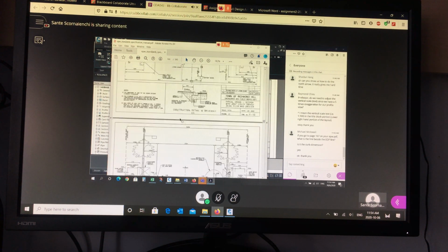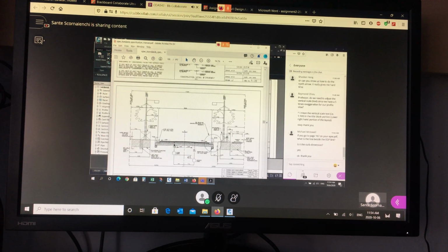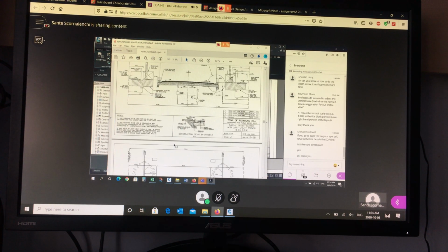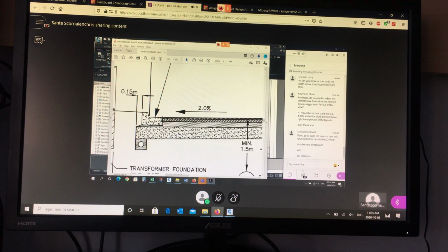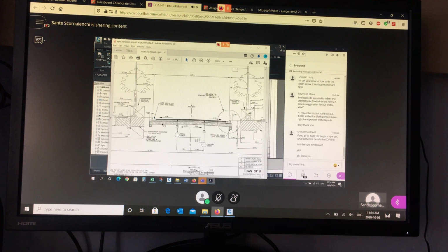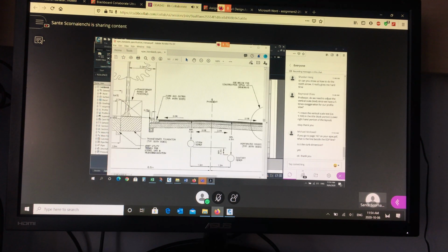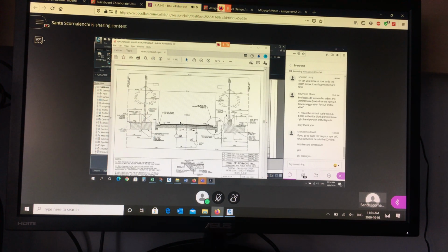Some standards will show you this is the gutter line. This one. Okay, local roads and collectors aren't that big a deal. But if you go to a freeway or an arterial road, the pavement width actually is from edge of asphalt to edge of asphalt. That width of the gutter is not included in the pavement definition. So you really have to pay attention to the standard. The term pavement is not always the edge of asphalt, is not always the gutter line. It depends on the standard you're using. In Richmond Hill, it means gutter line. Okay, and I'm not doing that to confuse you, that's just the language that's used, so you have to get used to it.